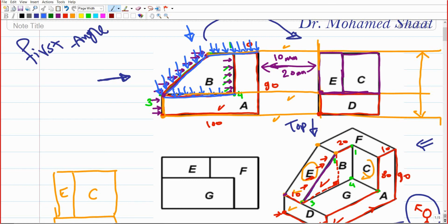Generally speaking, we have three lines that should be projected down. If we choose this first horizontal line, from the start point, move down vertical. And from its end, move down vertical, a very light line that is barely seen. And the inclined surface, do the same. From the start point, move down. From the end point, move down. And for this horizontal line, from the start point, move down. From the end point, move down. So we end up with four lines already projected from the top view.